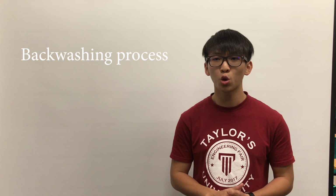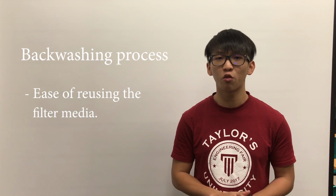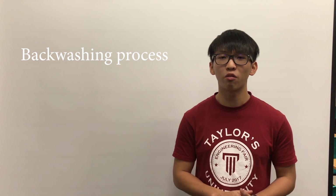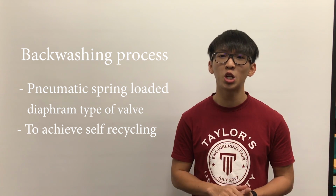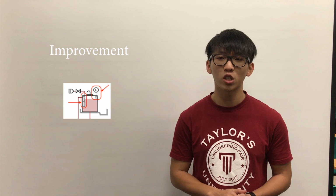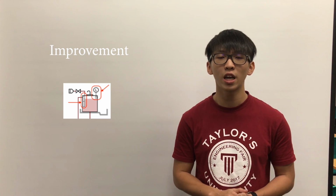Backwashing process is also built in the chlorination system for the ease of reusing the filter media. Backwashing process is accompanied with a pneumatic spring-loaded diaphragm type of valve to achieve self-recycling of the filter media to achieve smooth chlorination flow. Lastly, for the first chlorination storage vessel, the level meter can be reduced from 2 to 1 if the costing is too high.